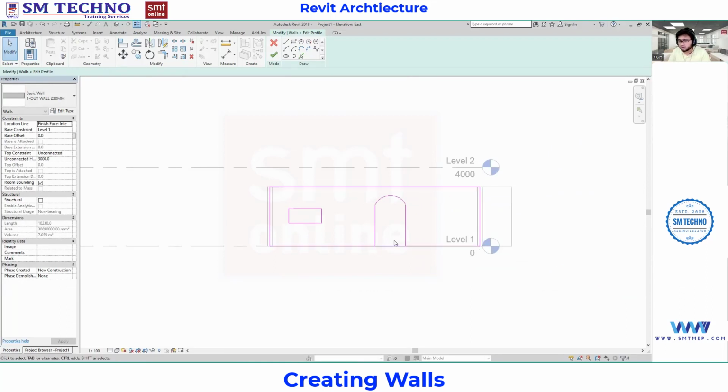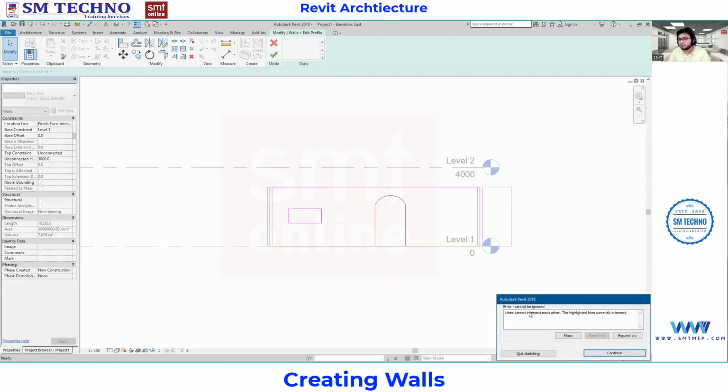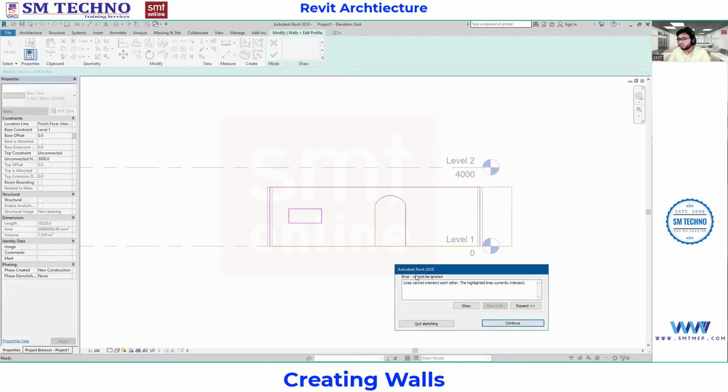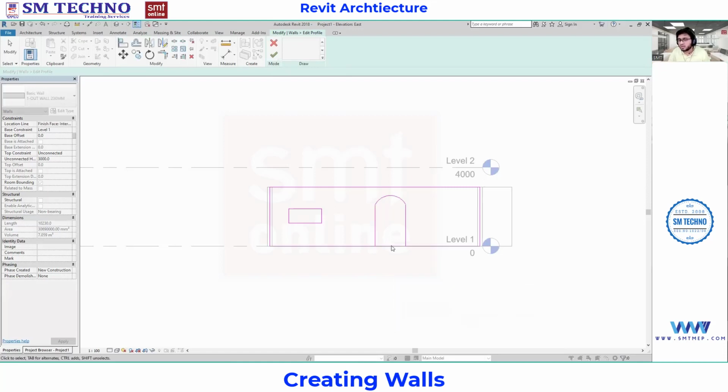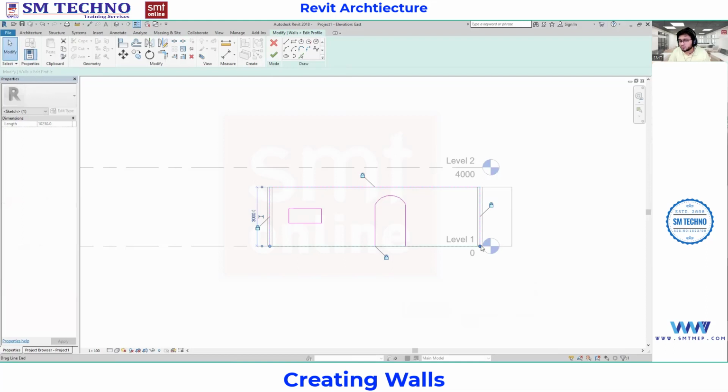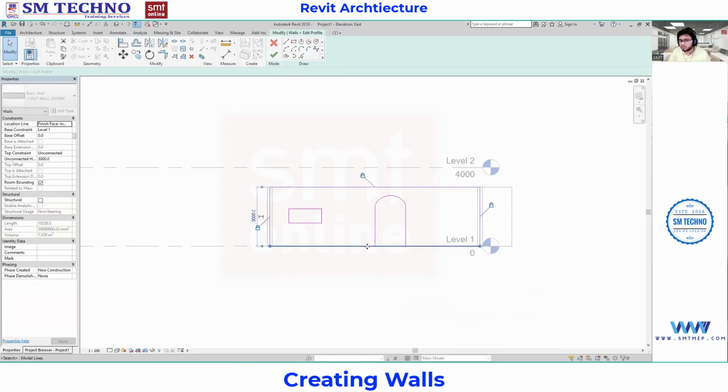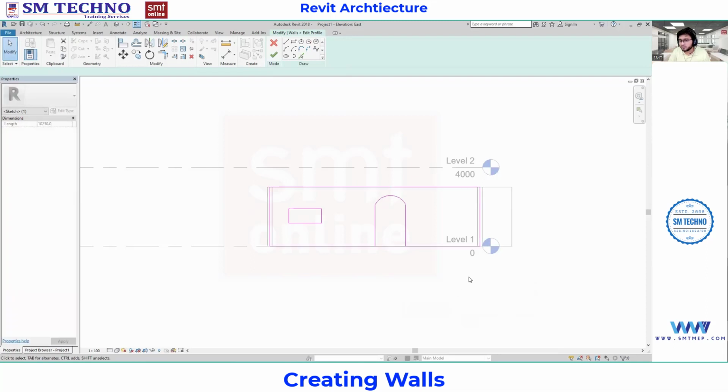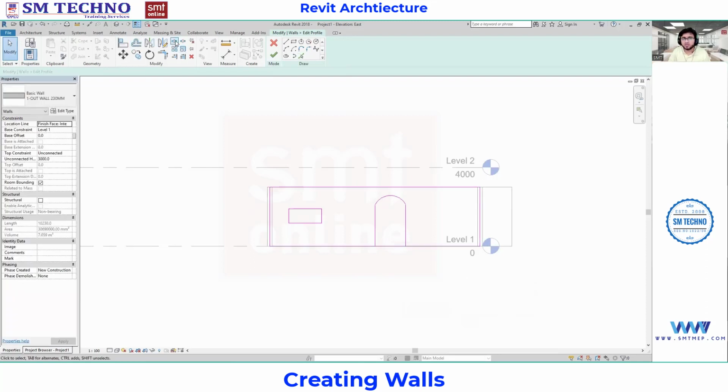So this should be open. We have to keep it open because the path should go something like this. There should be no line over here. If you are going to finish the sketch like this, it will give you the warning message. Can you see? It will give you the warning message. So we have to first make an opening over here. You can drag a line from here to here and place it. It is actually in a block mode. You can drag and place from here to here. But the simple way that I suggest is, here you can see we have got the Split Element option.